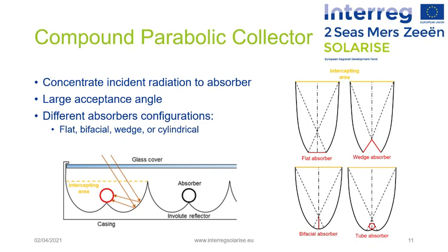They are then stationary systems, but they are nevertheless concentrated solar collectors, which can be seen as an exception from the two main categories described before. They have the capability of reflecting to the absorber all of the incident radiation within wide limits. The necessity of moving the concentrator to accommodate the changing solar orientation can be reduced by using a trough with two sections of parabola facing each other.